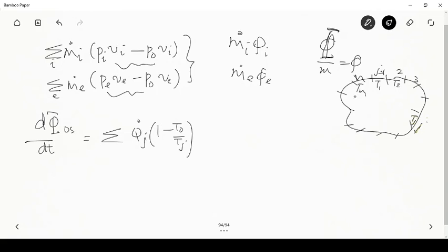Okay, so then at every boundary, if there is also heat coming in, let's say Q dot j is the energy that's coming in that segment, then Q dot j into (1 minus T naught by Tj) is the exergy inflow accompanying heat transfer. Then you also add minus W dot by the object or the open system, minus P naught into dV by dt.